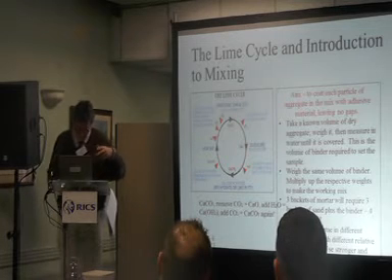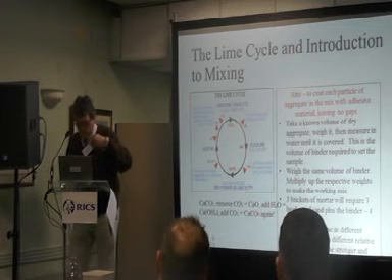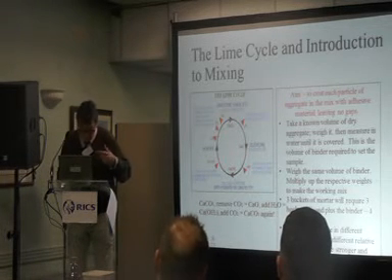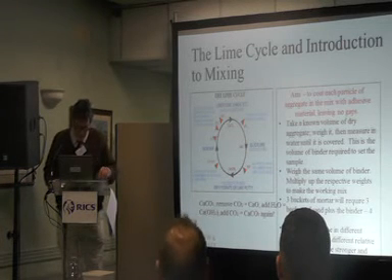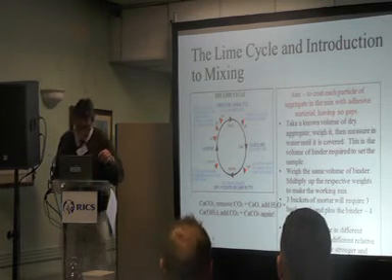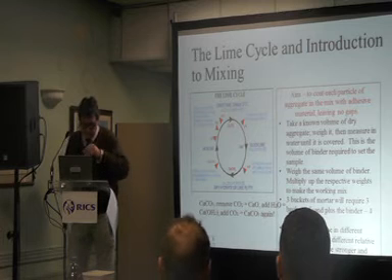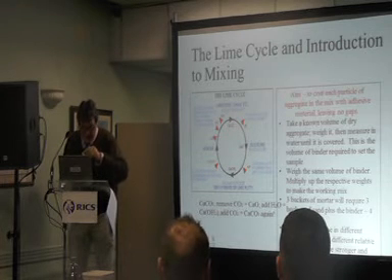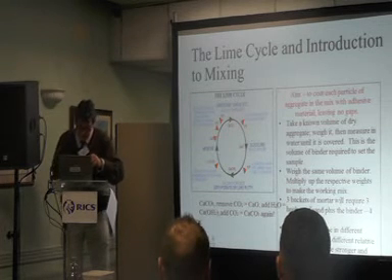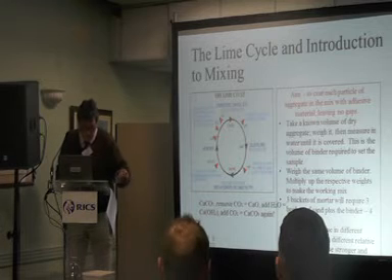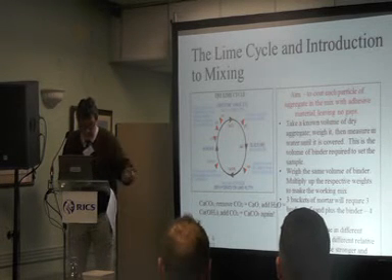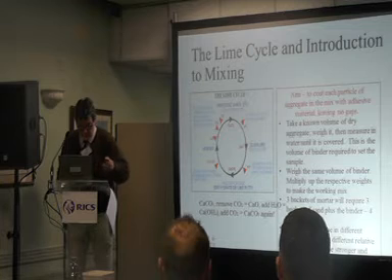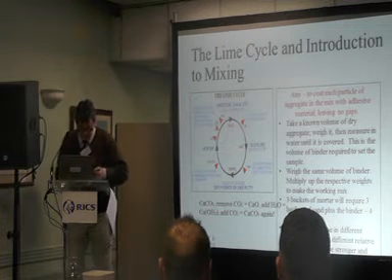I'm obviously skipping what you do if you've got a mix of different aggregates and pozzolans and all the rest of it, but just in basic terms, 3 buckets of mortar will need 3 buckets of sand and your binder. So 4 into 3 does go. You might take 3 buckets of sand, 1 bucket of lime, and make 3 buckets of mortar.